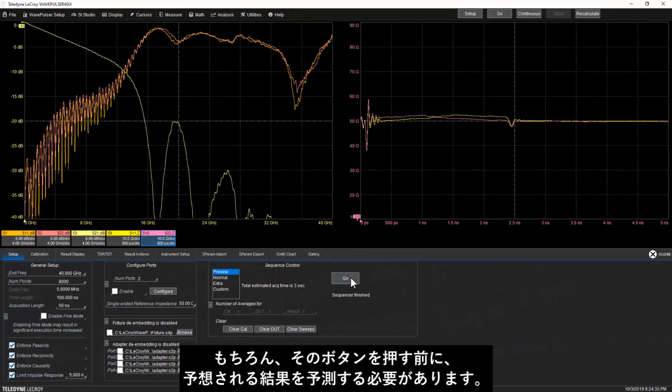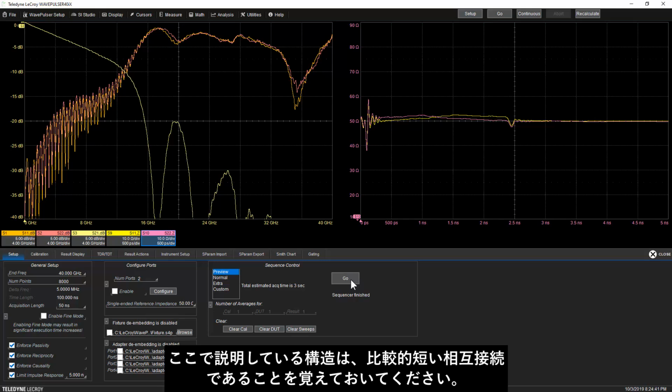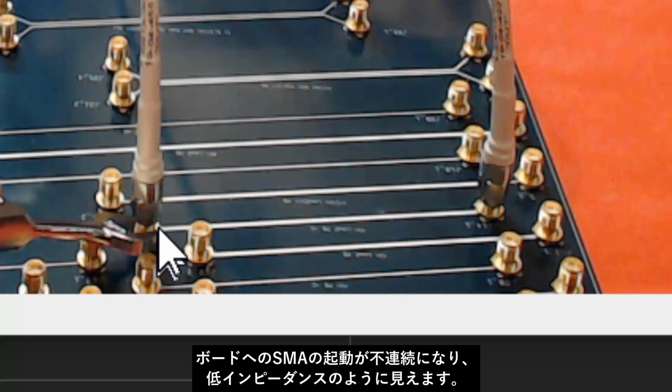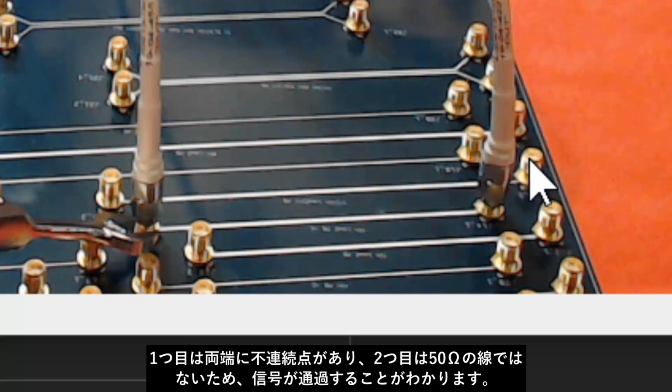We'll take the data, and of course, before we push that button, we want to anticipate what we expect to see. Remember, this structure that we're looking at is a relatively short interconnect. It's a 4-inch long trace. We've got the cables connected. We're going to see the discontinuity of the SMA launch into the board, and it's going to look like a low impedance. And so we're going to see ripples in the return loss quite a bit because number one, we have the discontinuity at the ends, and number two, it's not a 50 ohm line.